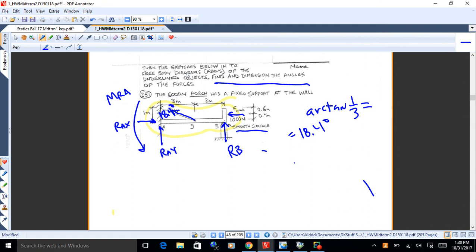Yeah, question there. Isn't the force of wind pressure? Yeah, the force of wind is a pressure, right? It's distributed over the side of the porch. It looks like that's probably been what I call resolved into a point load. So the pressure has been multiplied by the area already, and we have an assumption of a wind force. So someone's done a step already on this one. Okay. Other questions?